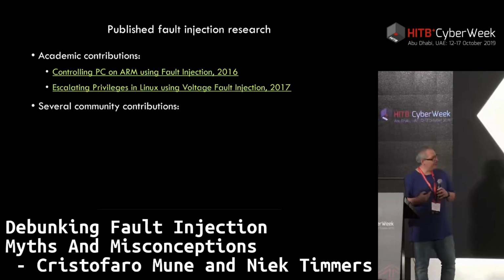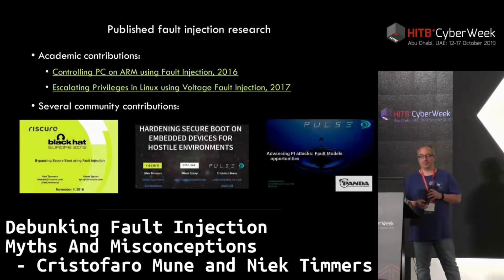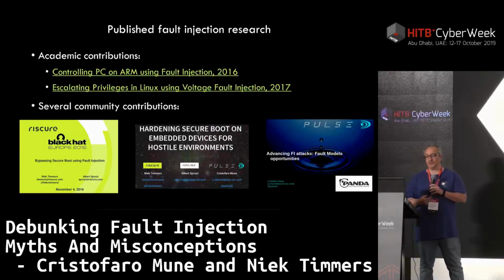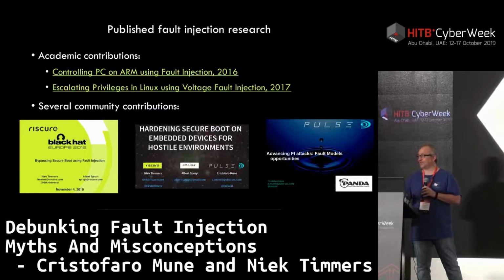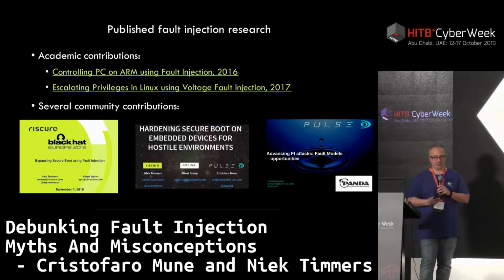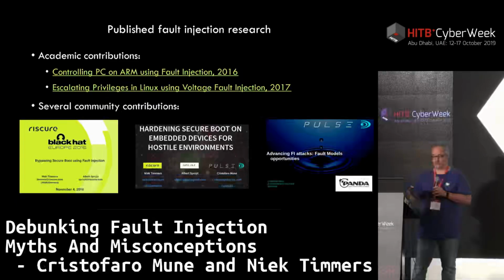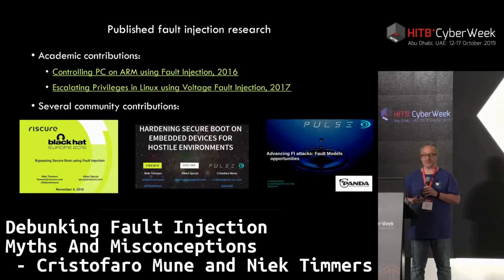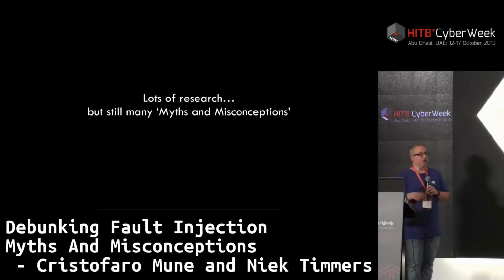Along with that, we have also had several community contributions. First, bypassing secure boot using fault injection. Again, Albert and Nick really did a great job on this. We extended our results in 2019, where we presented how to bypass secure boot, but with encryption on top, without having the need of a key. So basically, we need one glitch, no key needed, and we can bypass that kind of secure boot, even if there is encryption on top. And also, we explored a few different possibilities in another presentation. So there is lots of research being done, but there are still many myths and misconceptions in this field.